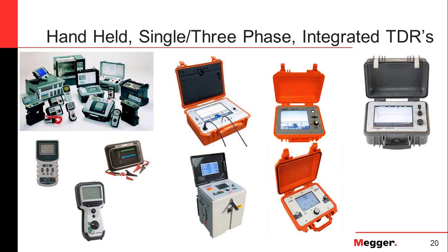You would use a voltage gradient method. So depending on what type of cable construction you're working with, that dictates what the best troubleshooting techniques are. And arc reflection on a medium voltage shielded cable is usually the right technique. But for other type cables, there are other techniques.